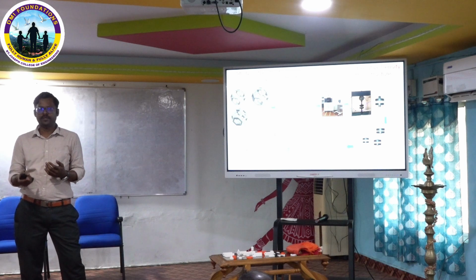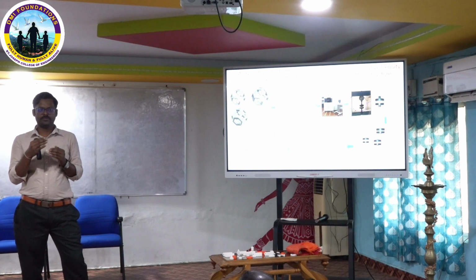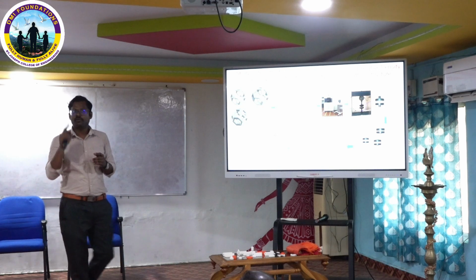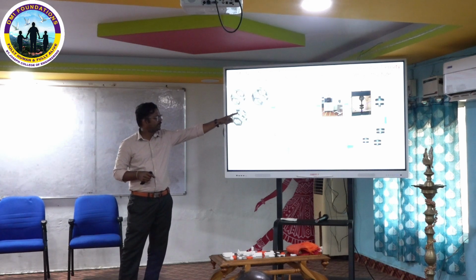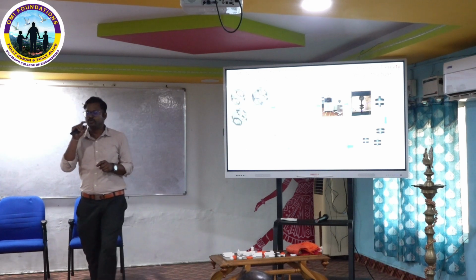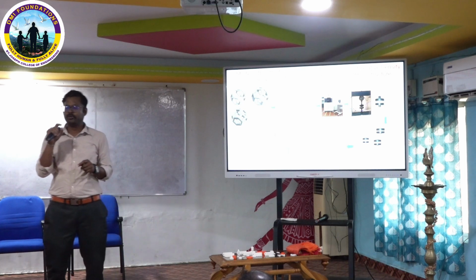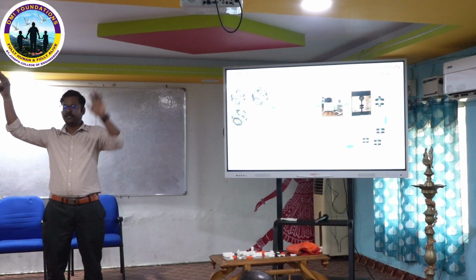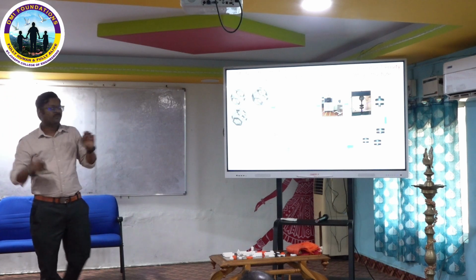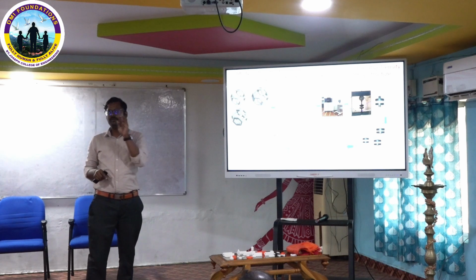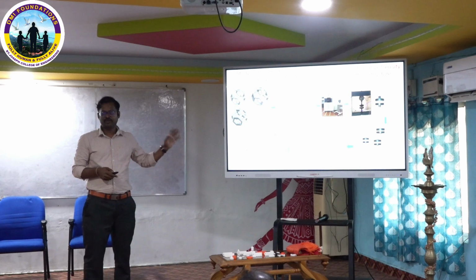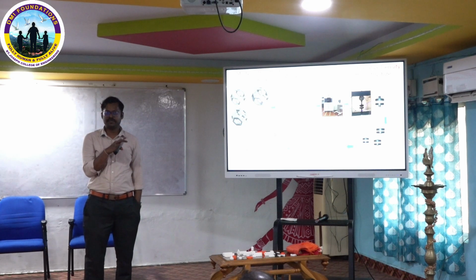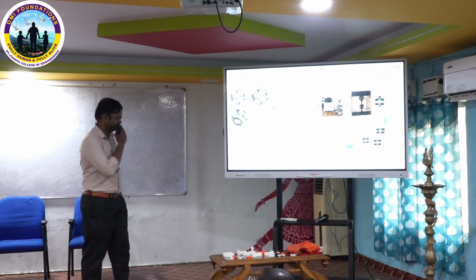We take the powder. Why I am telling this is the cost of the powder, especially buying from EOS or German based, is high. 1 kg of powder costs around 10,000 rupees. For this one component I have to print with build now, it is 2.5 centimeter height. I have to put 5 kilo of powder. Here 2.5, here 2.5 minimum. So for a single build I have to put 50,000 worth of powder. So we need to be more conscious of this when we go for fabrication. That is not that much rocket science. By practice it will come, sir.